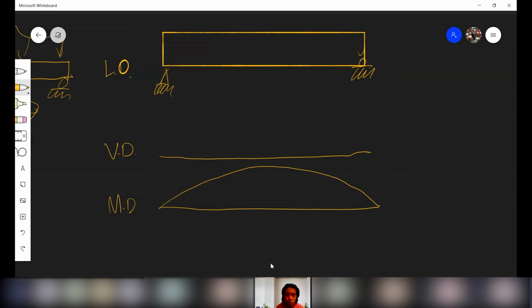Very good. Obviously, wherever the stress is maximum, that is where your beam will most likely fail, if your beam will fail. Okay? Naturally, it's there at the maximum stress. And the maximum stress is where the maximum moment occurs.